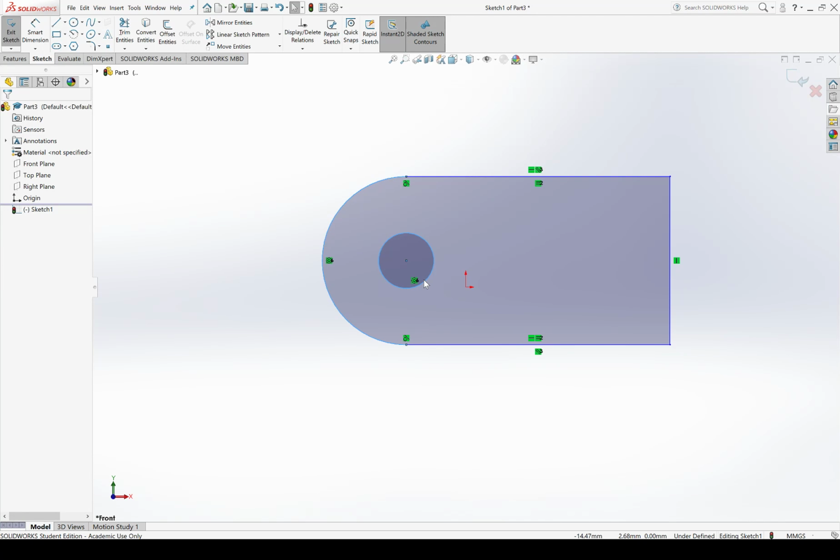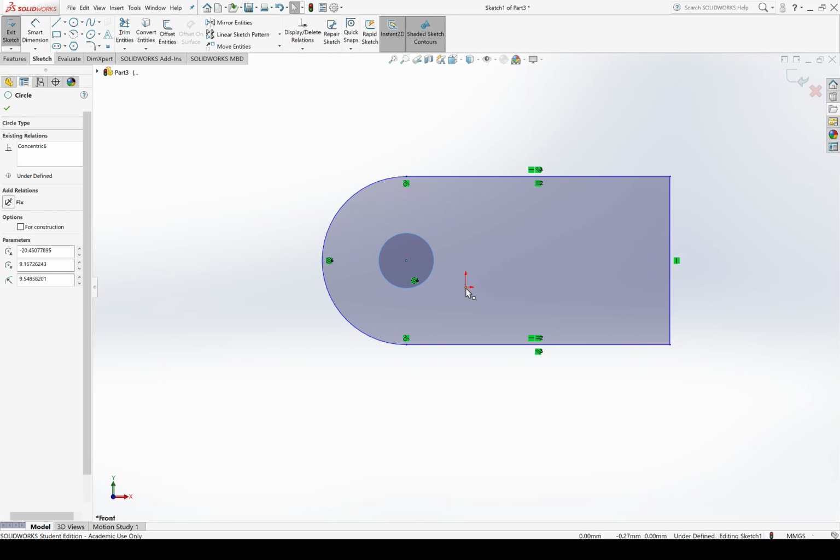As we get further along, once we start dealing with assemblies, the origin of the part is more important because that affects how you relate parts together in an assembly. If we were actually positioning this bracket so that the pin could mate with a hole on a different part, the origin position might be more important. But here it's arbitrary. So I'll position the origin such that it's on the center of this hole cutout.